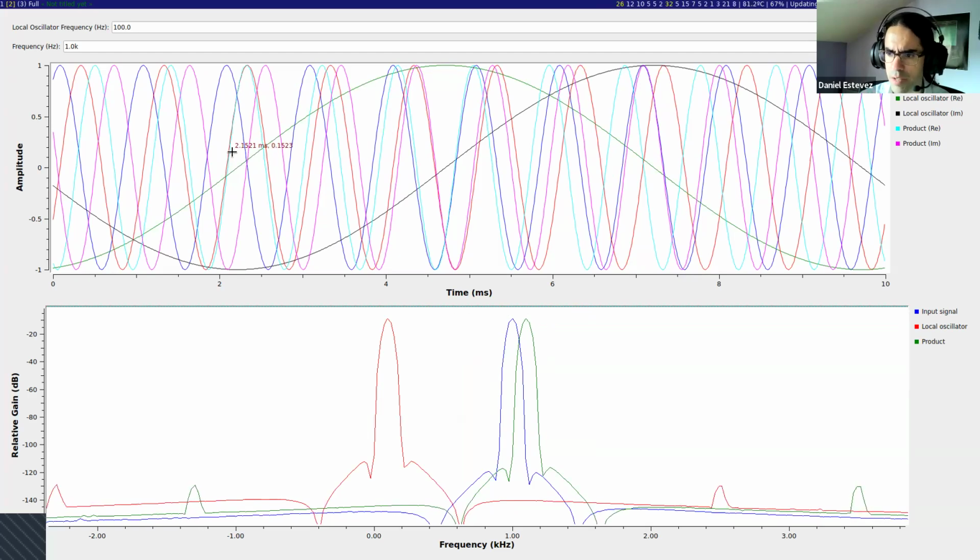So think of them as exponential functions. They have the frequency and the time on the exponent. If we multiply two exponential functions, that is equivalent to adding the exponents. So since we add the exponents, we add the frequencies. Those are the things which are on the exponent. So that is the formula. That is the mathematical explanation for why when we multiply these complex cosines or these complex exponentials, we get only the sum of frequencies.